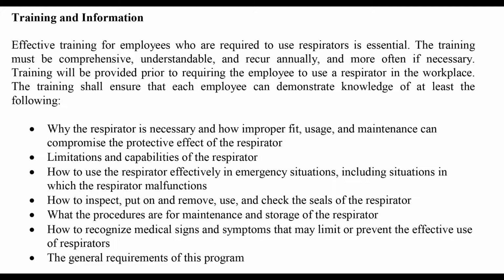Training and information. Effective training for employees who are required to use respirators is essential. The training must be comprehensive, understandable, and recur annually, and more often if necessary. Training shall be provided prior to requiring the employee to use a respirator in the workplace.